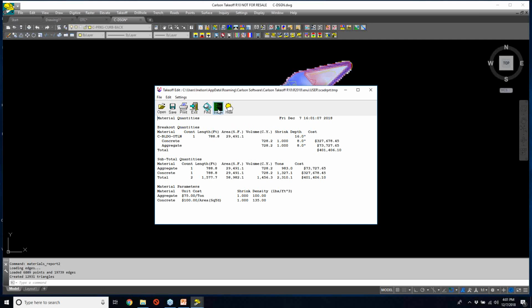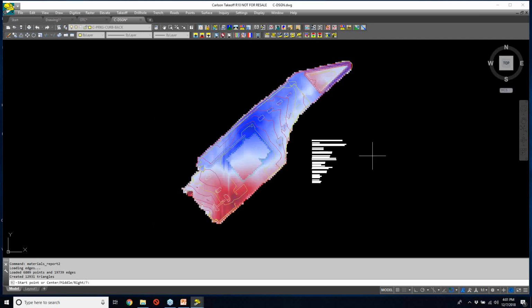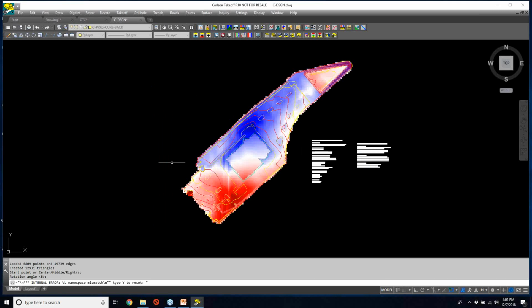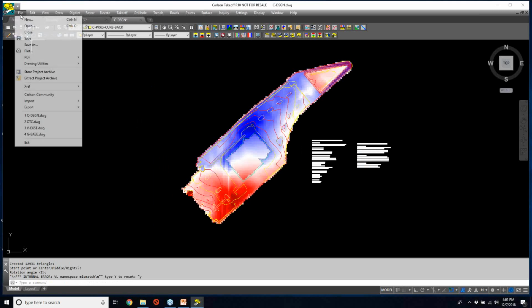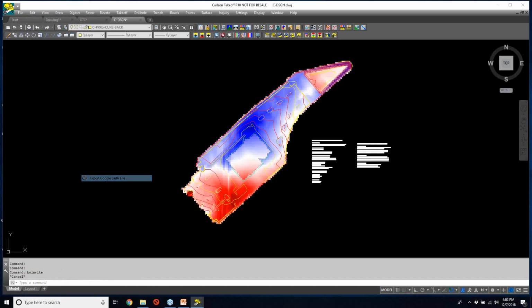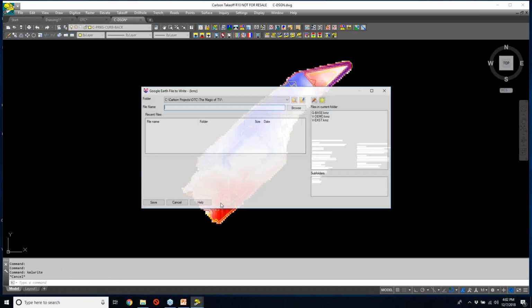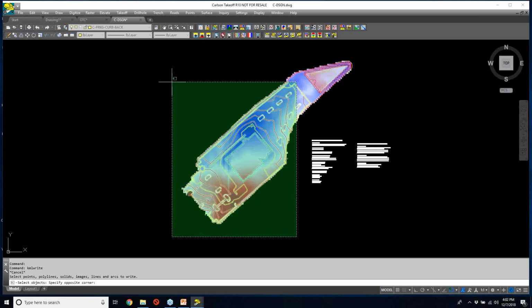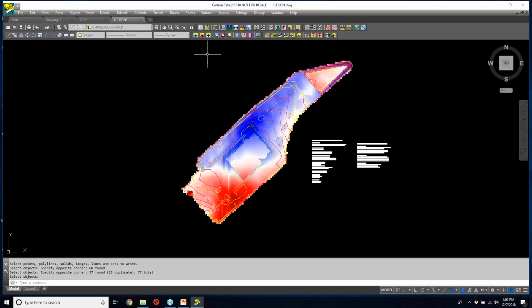And again, put that information on the screen, choose OK, and we can go right out to here again. And then, one of the things that people like to see as we roll this all out is that this is all information that we can send out and report back out to Google Earth. So as we are properly geo-referenced, we can say, let's export out a Google Earth file now, and we'll just say OK. And let's just write this out to my OTC file. And we will write out all this data, and send it out and take a peek.